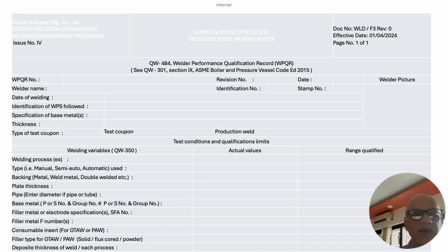So these are all the factors which decide the coating factor and the way the welder has really maneuvered and the accessibility issue he has seen. If you have used a very thin electrode which is non-synthetic, and then you are using a synthetic electrode, your deposition may be higher, your diameter will be higher, and then accessibility, the visibility of the weld comes into the picture.